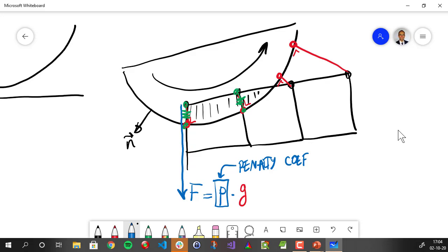The best value is, let's say, plus infinity, so that each time the node crosses the boundary, a force in this direction will be created, which is infinite, so that it jumps out of the forbidden area. But of course, with this kind of value in a numerical code, nothing works. So you must choose very high numbers, for example, 10 to the power 6.